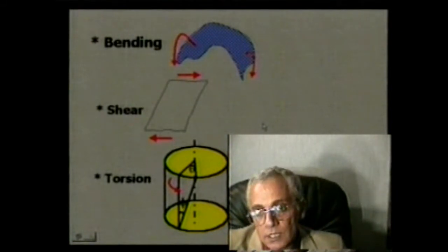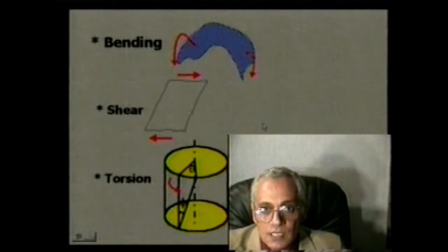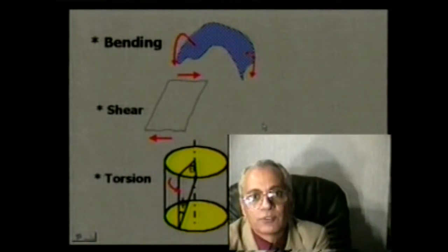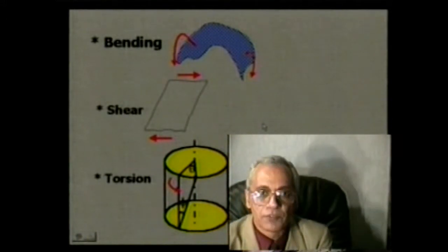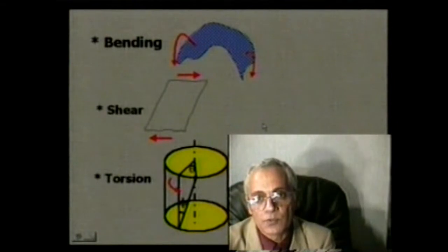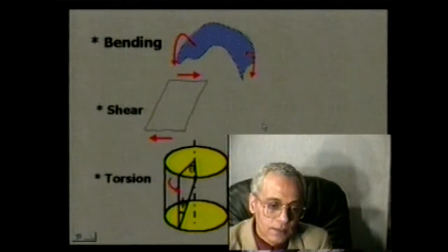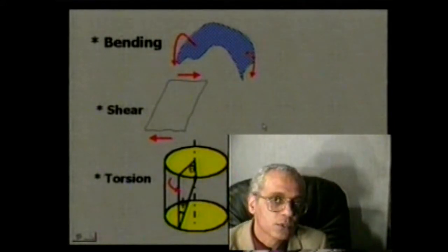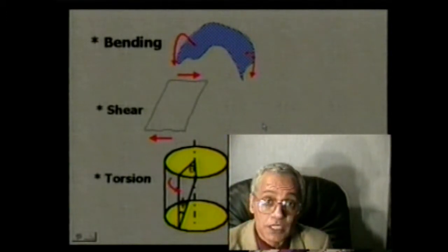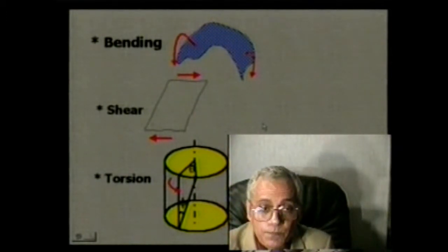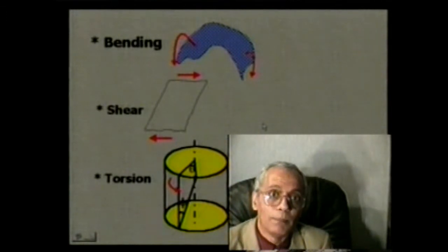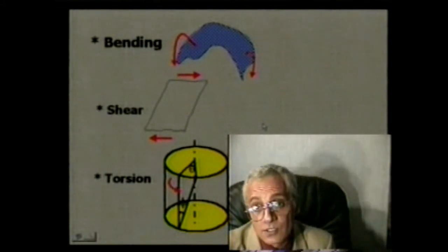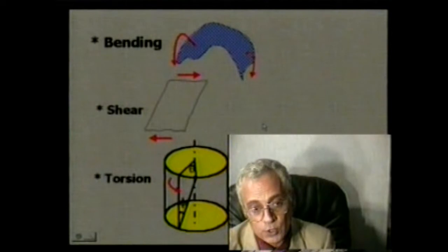We can look at the fiber flow and see that in our process of manipulating the fibers to make a yarn, we have to use different modes of deformation and different types of stresses. As a matter of fact, fibers during processing are subject to almost all modes of deformation. They are being stretched, compressed, pressed, bent, twisted, and rubbed against one another and against different solid surfaces during processing.